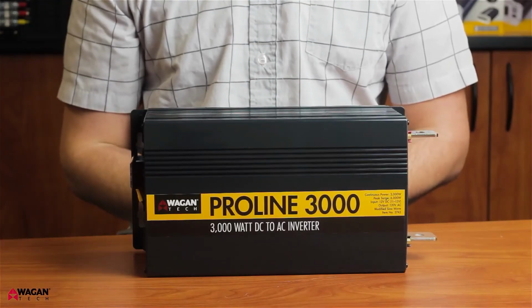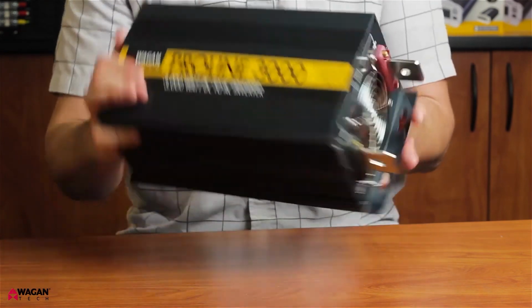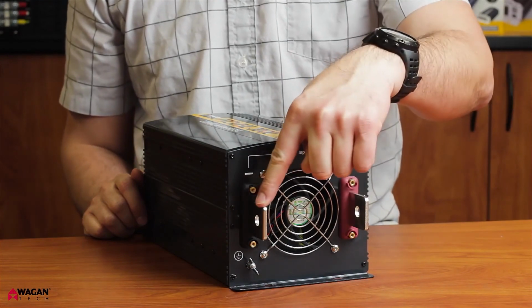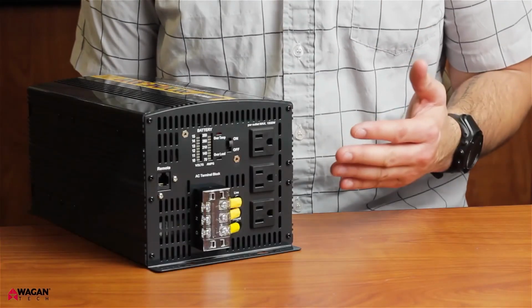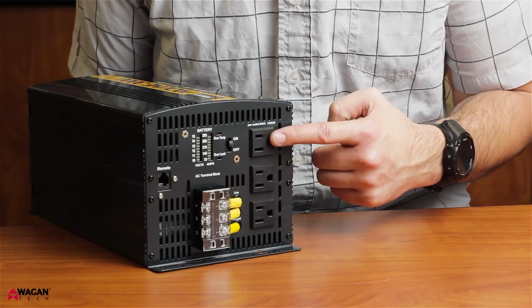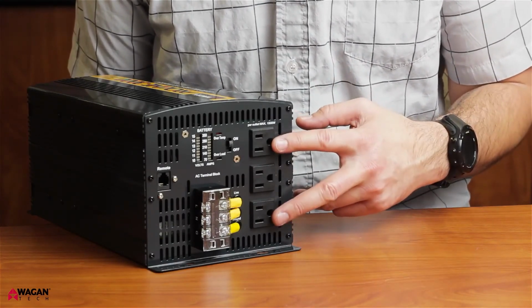The new ProLine inverters feature a lightweight aluminum case with an attractive black finish. On the rear of the device, there's a heavy-duty positive terminal, negative terminal, ground terminal, and a high-speed cooling fan. The 3000 and 5000 watt models feature 3 AC outlets capable of 1500 watts each, whereas the 8000 and 10000 watt models have 4 AC outlets.